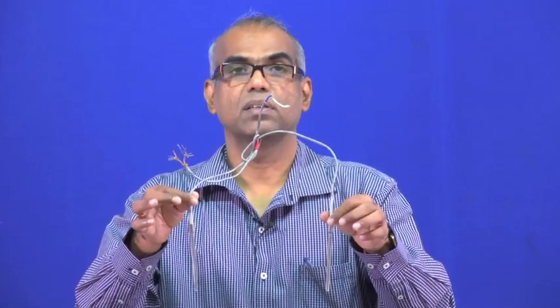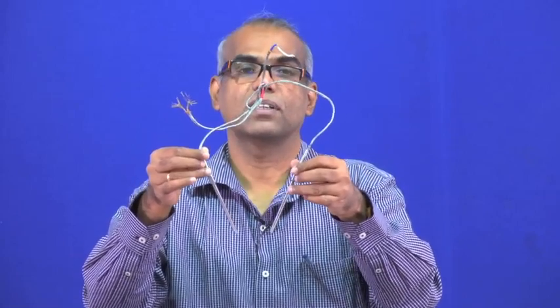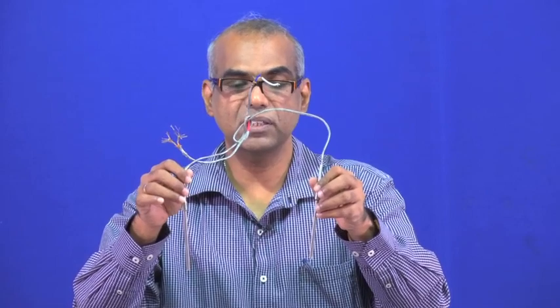You are already putting this into 0 degrees Celsius, so no correction is needed. If it is not put at 0 degrees Celsius, but some other temperature, then a correction is needed. What correction will be added? The EMF that will be produced when the two junctions are kept at the reference temperature you are using now and 0 degrees Celsius. So, this is a thermocouple. A thermocouple will always have two such elements. Inside these two protective cases there are two joints: one is the hot junction or measurement junction, another is the cold junction or reference junction.